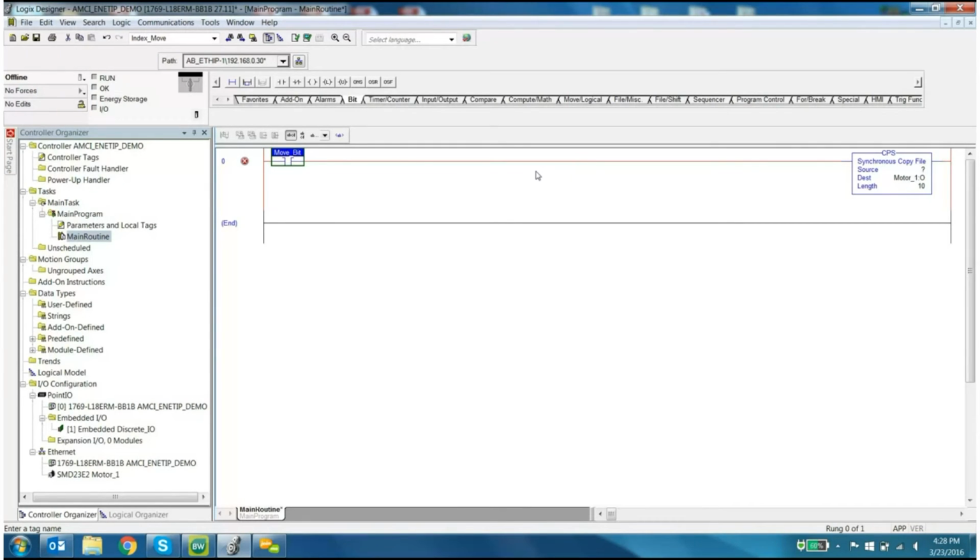You also need to understand that when you're doing a move, the move occurs on the transition of that particular command bit from 0 to 1. So if you're doing a series of relative moves, whether they're the same distance or different distances, it still needs to see a transition of 0 to 1 on that relative move bit.